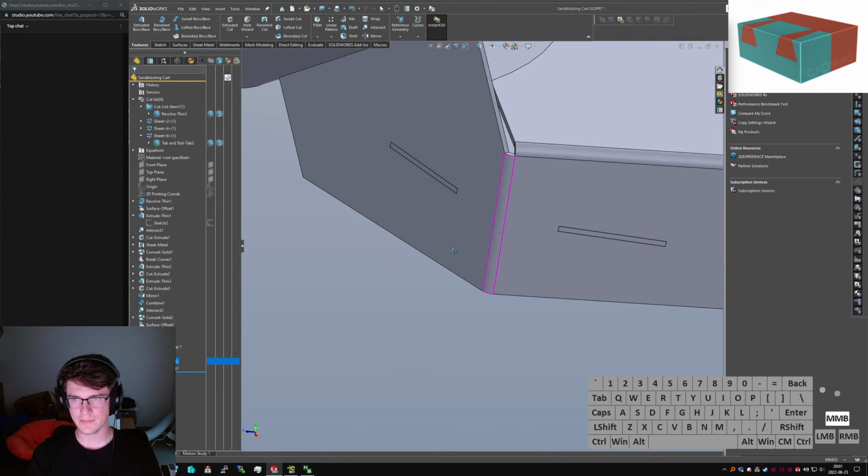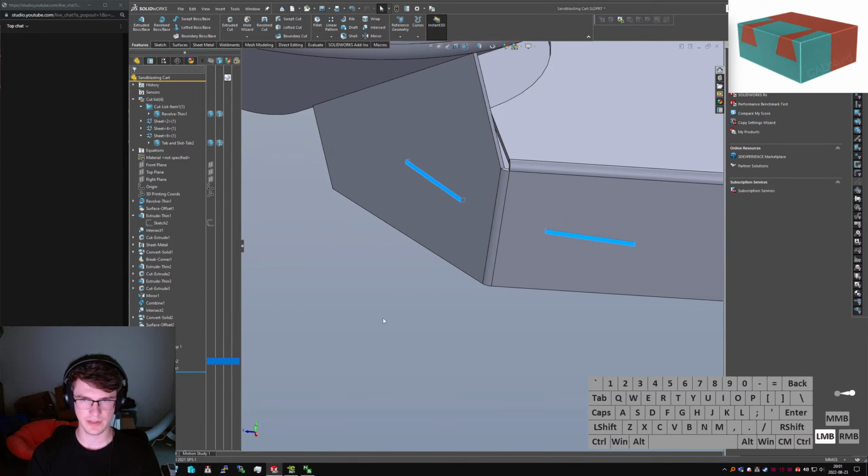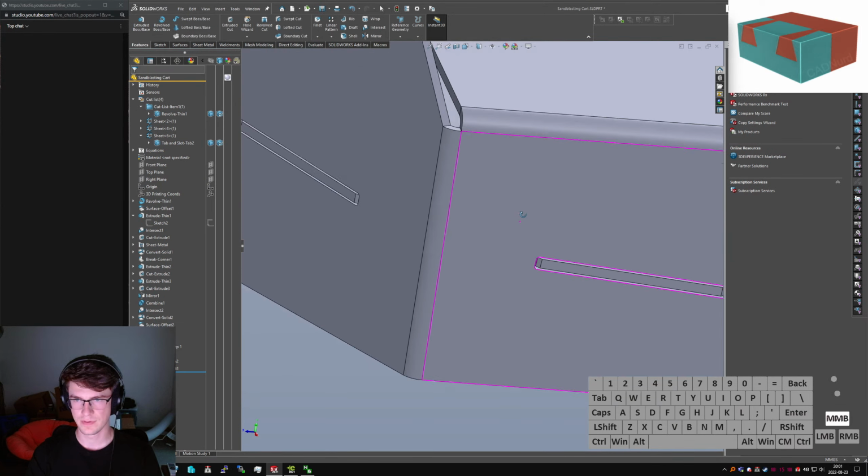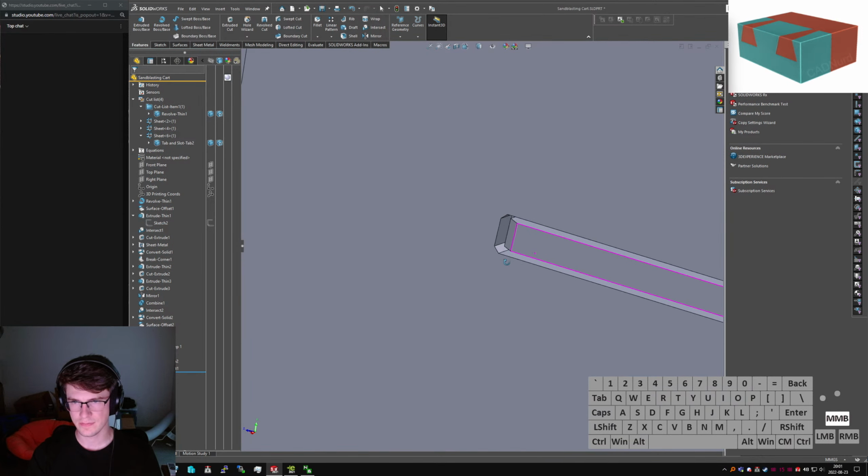So now, I should probably do that with some clearance. I just type just a little bit of cut on there to make things nice. Maybe 1 millimeter clearance. And then probably some chamfer corners or something just to make sure that it's, you know. Yeah, there we go. Maybe fillet corners would be better if you were worried about kerf.